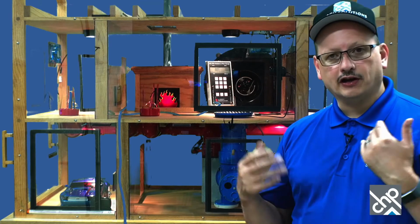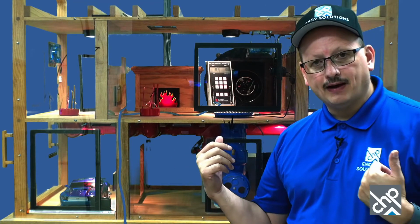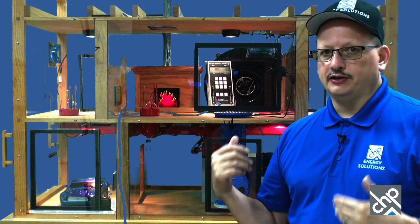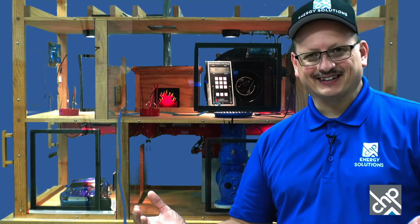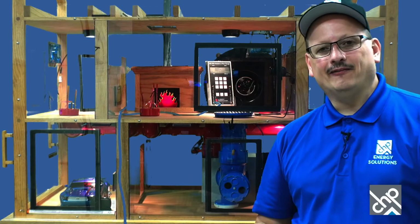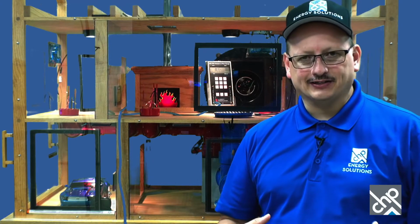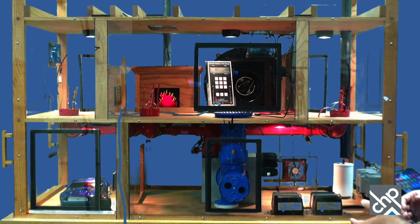Because when we start talking about CAZ testing, you start putting all this stuff together, you have to think about, okay, I'm doing my CAZ test, and everything was good until this happened. And so you want to know what this happened was. Was it when the air handler came on? Was it when the doors closed? Was it when the exhaust fans came on? Those kinds of things.